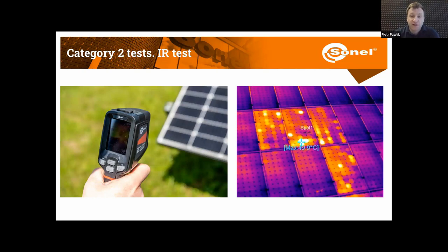So for the general, the temperature difference between hotspot and normally operating array is most important. It should be noted that array temperature is a function of irradiance, wind speed, and ambient temperature, which vary significantly throughout the daylight hours.